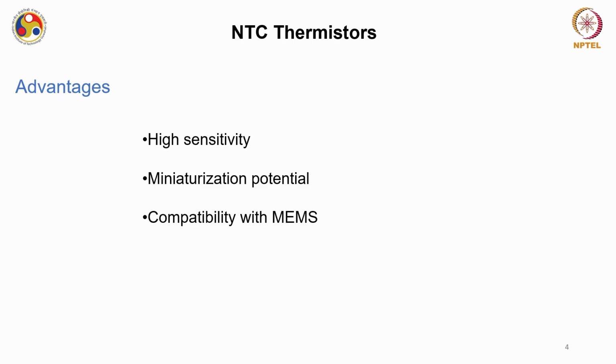The advantage of these NTC thermistors is their high sensitivity. These NTCs usually have higher sensitivity as compared to their counterparts like PTC as well as the RTDs. They can be miniaturized very similar to the PTCs, and the process is compatible with CMOS fabrication processes as well as with MEMS technology. Particularly, the fabrication temperatures of these NTCs are favorable for the currently existing MEMS technologies.